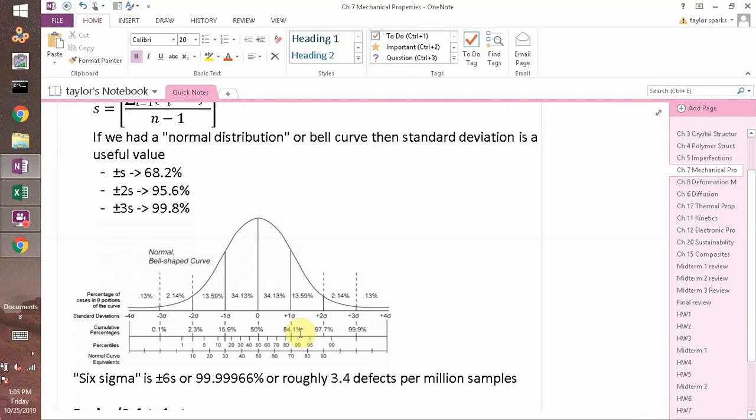And if you have a really important thing that you cannot have fail, because it's going to kill somebody, like a pacemaker, for example, you would strive for 6 sigma fabrication in your products, so that only 3.4 defects in a million fail. Maybe that number's not even good enough. Maybe it has to be even better than that, right? But the point is, this approach lets you at least define those terms. Now, how on earth did they get to this 3.4 defects per million are going to fail? That's where Weibull Statistics comes in and helps make it easier for us, okay?